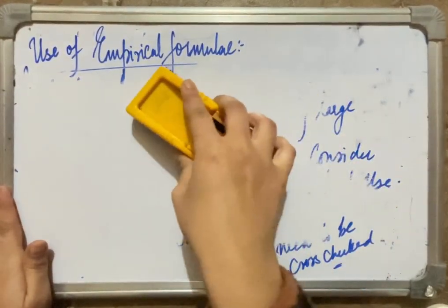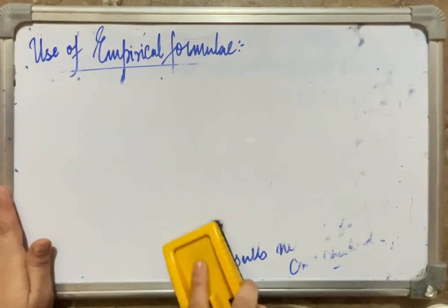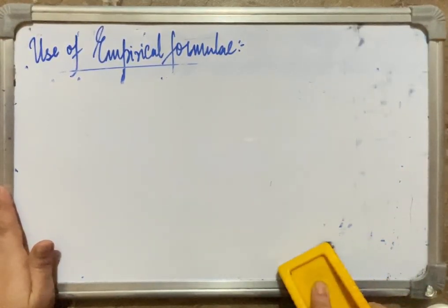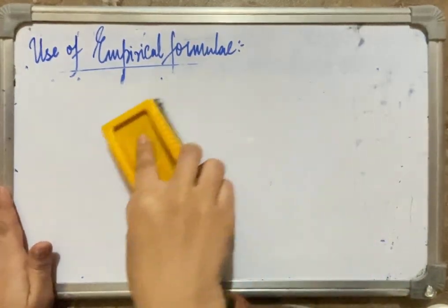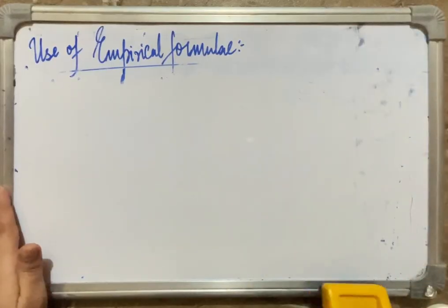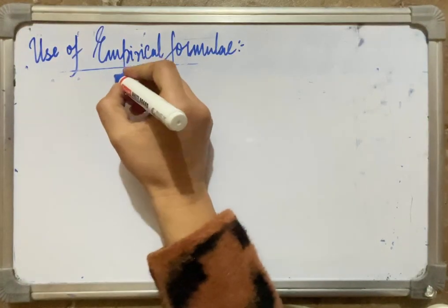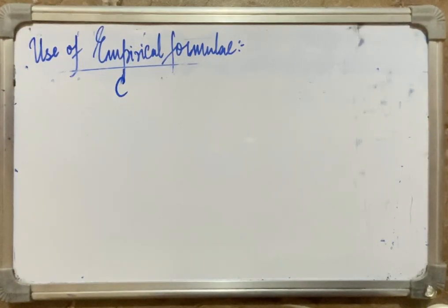So we studied about the empirical formula for determination of the maximum discharge of river. We studied the Dickens formula, the Ali Nawaz Jung Bahadur's formula, the Rice formula, and the English formula, all right? But it should, however, be remembered that these empirical formulas are oversimplified and they give reliable results only if the correct value of C is adopted.